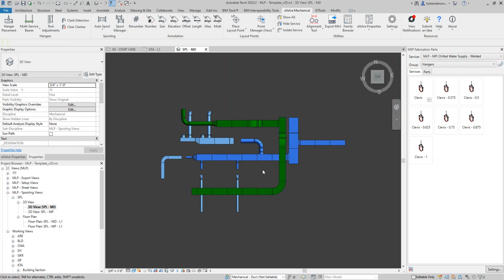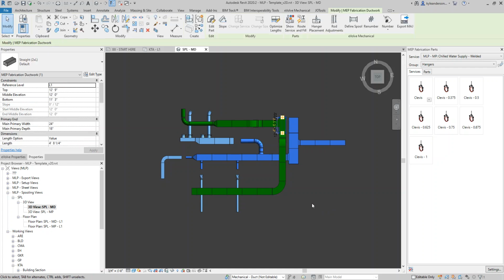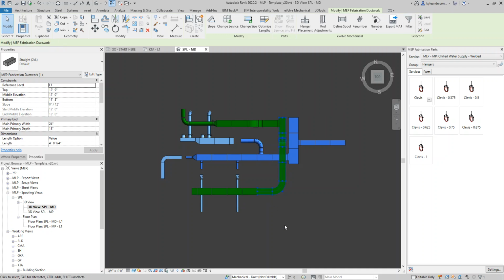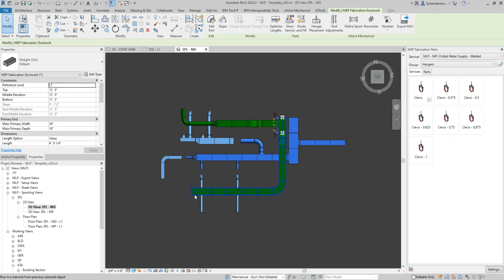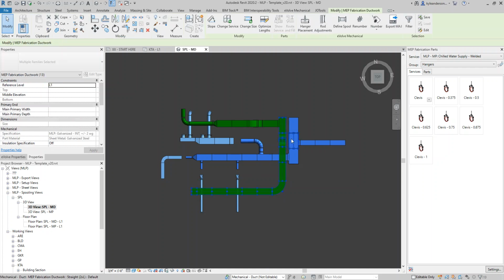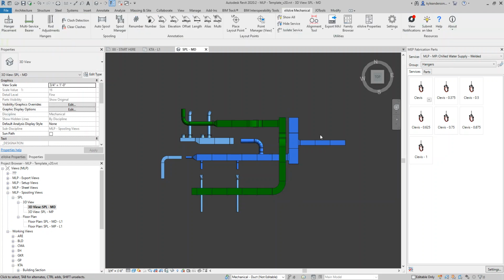As far as the width is concerned, the width refers to how much left and right I want to include with that. So in this case, if I had it at 10 or 15 feet, it might turn the corner and include this first piece on it. In this case, I've got it set to 40 feet, so it's actually going to spool out this entire run because it's within those constraints, lengthwise 40 feet, widthwise 40 feet.